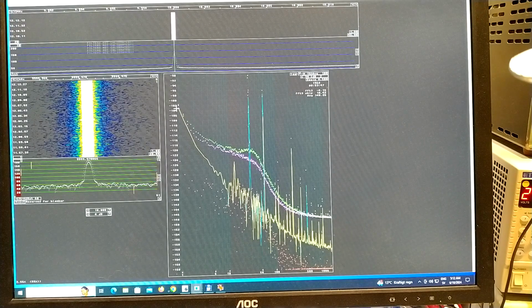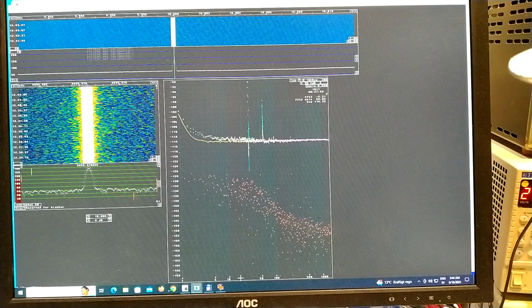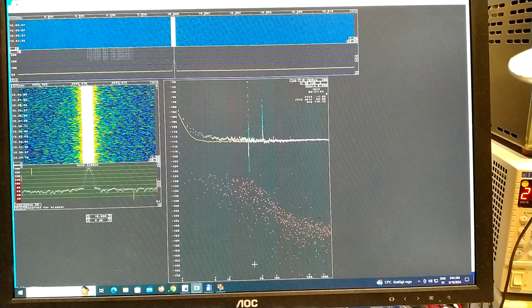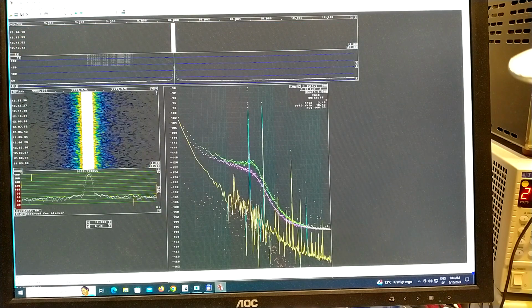It goes from about minus 102 dBc per Hertz at 1 Hertz, and about minus 160 at 1 kilohertz. I have degraded the flat noise floor by adding a big attenuator followed by several amplifiers. This is what it looked like before, from minus 162 up to minus 102.